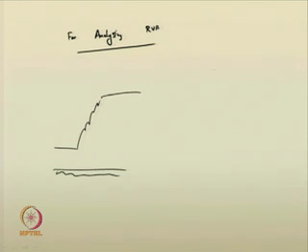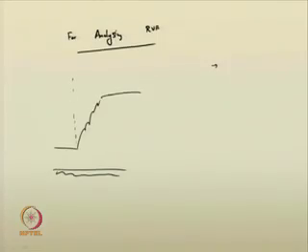So, if you use your standard continuum approach, that is, with a control volume, you have to select the control volume in such a way that it incorporates the entire details of the rapidly varied flow. So, here we are now taking the control volume as shown in the box here for the hydraulic jump.